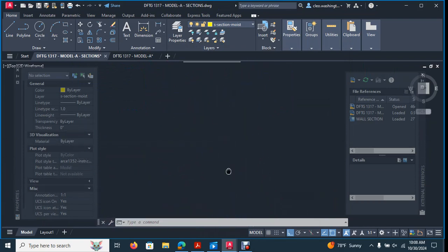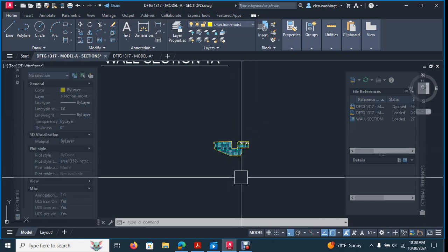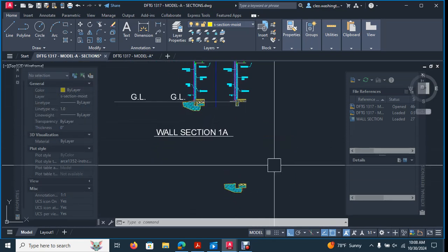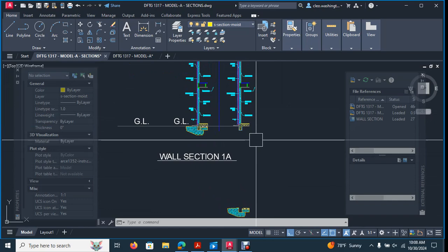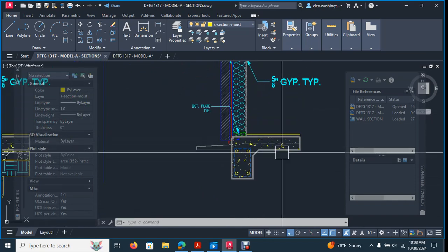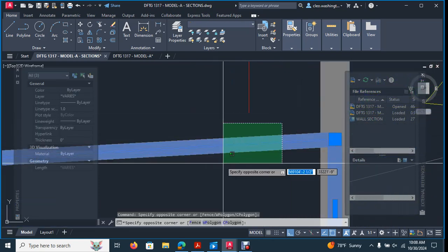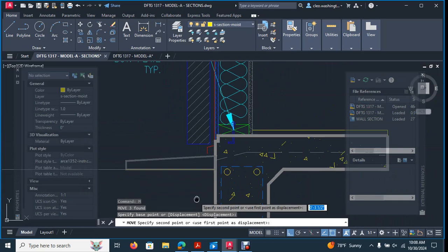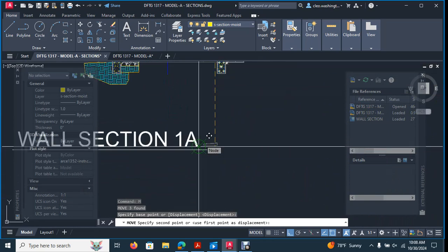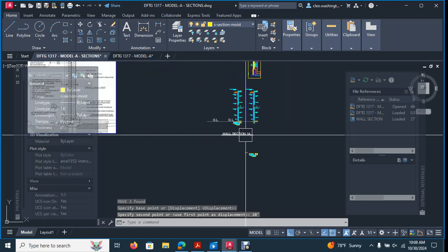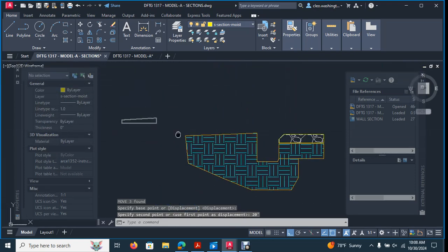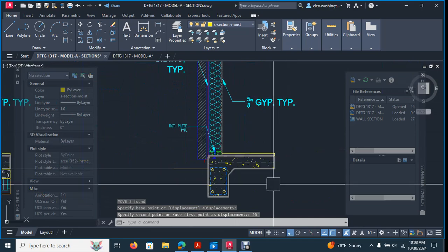so let's go ahead and make a modification at the slab. We already moved everything down. We moved it down 20 feet. That way, when you move it back, you can just move it back up 20 feet, and it'll be in the precise location where you need it to be. Let's actually take this guy and move it down 20 feet as well. Let's type in 20. So everything is right there. You can just move it back up 20 feet when you're ready for it.